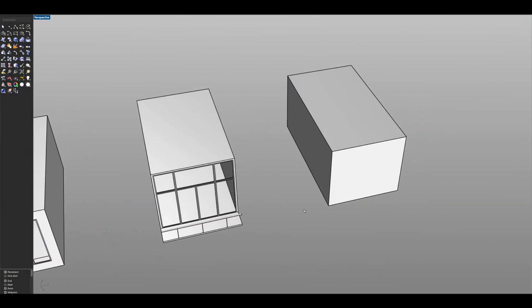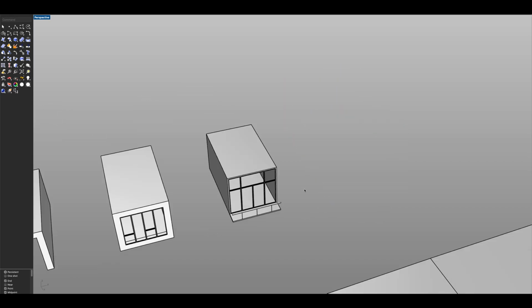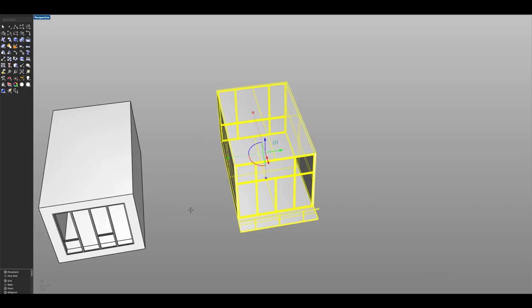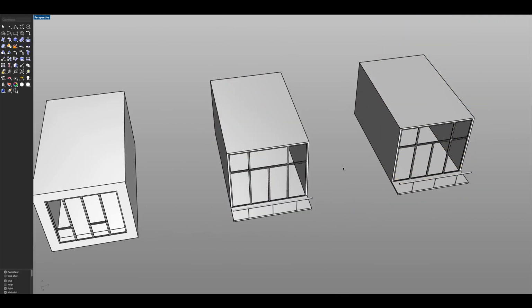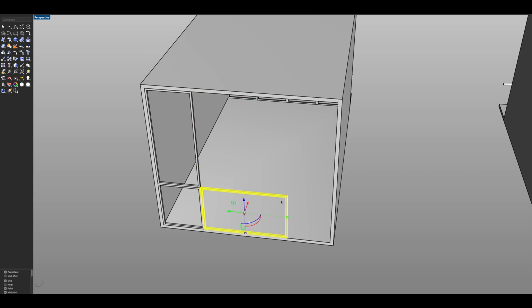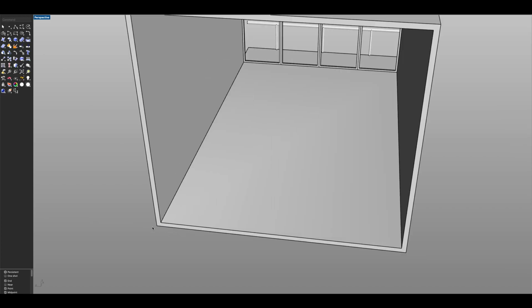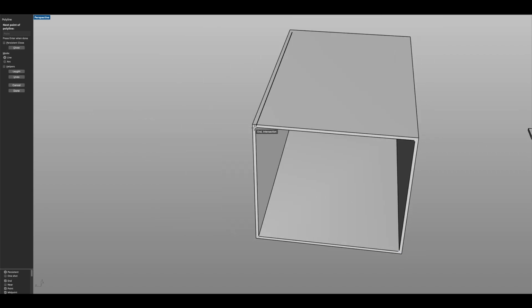And for our last Rhino element, to make this very quick, we really don't need this prep here. All we need to do is copy this one and push and place it on the side like this, and simply remove these windows back here, since the stair container, which is the model we're building now, has the back part completely shut. So we just need to build up a new curve here.